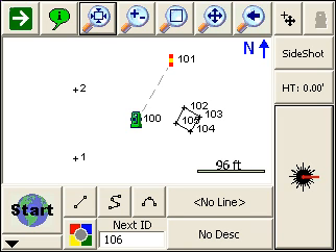This video will show you how you can use the RTS, Rotate Translate Scale command to adjust some points. What I've got here, this 1 and 2, these are some design points, and these 100 series points are what is being shot out in the field. So what we want to do here is adjust these points so that they line up with 1 and 2, where point 100 is going to go to point 1, point 101 to point 2, and everything is rotated and shifted down to match these. So we'll have the structure here roughly in this location.